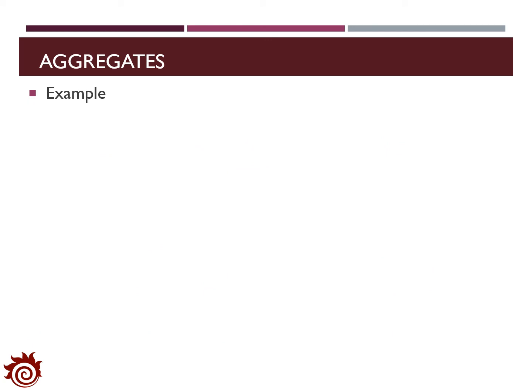Now we can check a base and subbase layer. The base layer is placed on top of the subbase. This means we will assume that the base is a filter and subbase is a soil. From the previous solutions, we can get a D15 filter for base and also D50.